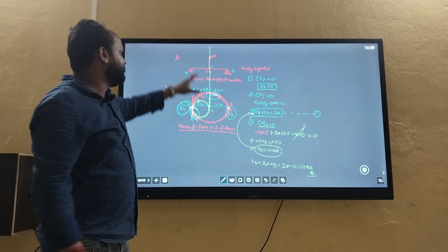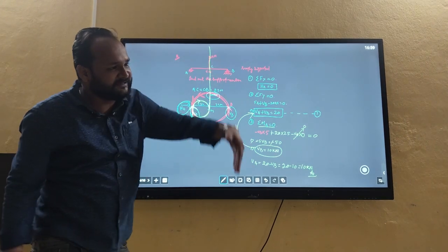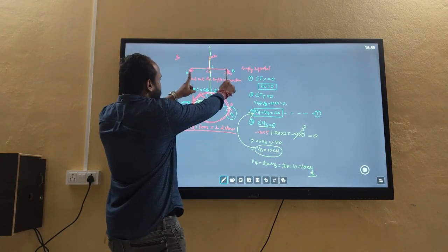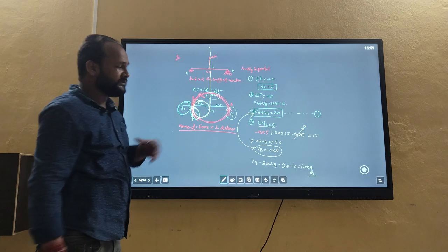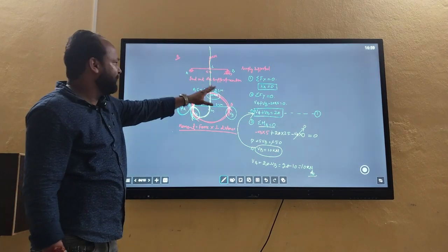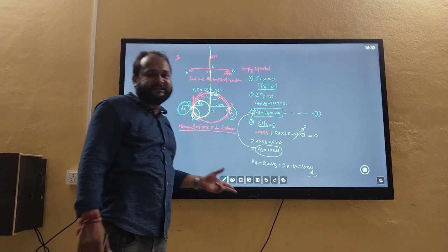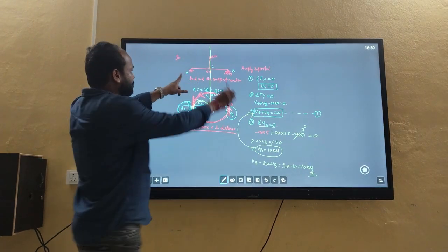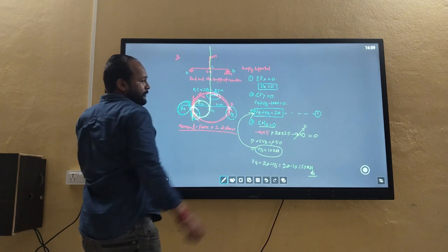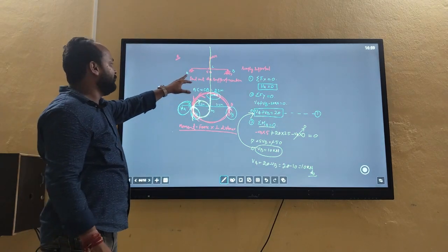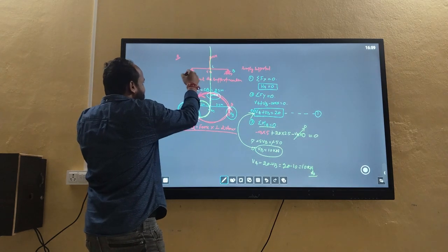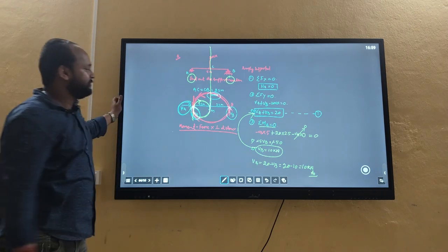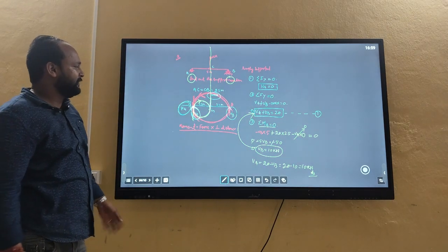By applying the logic, if an upward force of 20 kilonewton is there and two reaction forces are there, one at A and another at B, and the structure is stable, that means both the reaction forces are taking the same load. That's why the structure is stable. So if it is 20 and both the forces are contributing the same effort to make the structure stable, then obviously the point A reaction will carry 10 kilonewton as well as point B will also carry 10 kilonewton. So it is a symmetric section.